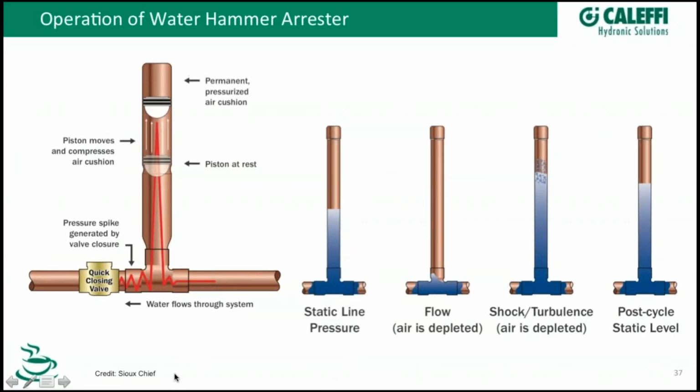And so here's probably a really good graphic that explains what happens when we quickly close this valve, and that shock wave now with this water hammer arrestor, it dissipates that. So think of this as almost like a shock absorber on your vehicle. It's got a piston in here and it's got a seal in here. And so there's an air chamber, a little air space up here separated from the water here. And so it just pushes that up there. This will probably bounce up and down there until that shock wave is dissipated.